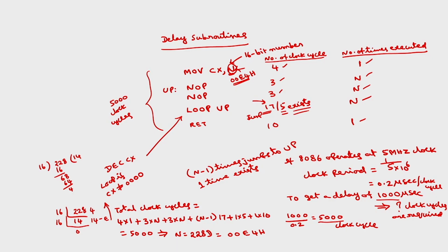Okay. So, this is about simple interfacing of an output device such as LED or CRO. You can generate a square wave of any desired frequency using 8086 and 8255. Similarly, you can blink the LED at any desired rate. Similarly, you can connect a switch also, an input device. So, I have discussed the output device. Now, I want to connect an input device to the 8086.